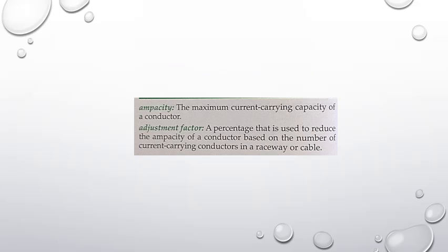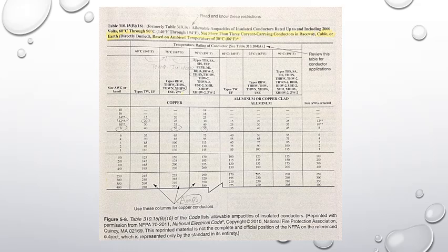if the wire will be installed in the following conditions. No more than 3 current carrying conductors in a raceway or cable. The maximum ambient temperature is 86 degrees Fahrenheit. The conductors have a rating of 0 through 2000 volts. To select the proper size conductor, you will have to know the type of conductor that will be used and the required amperage. You will also have to know how many current carrying conductors will be adjacent and the maximum ambient temperature. These last two requirements will be explained after this example.